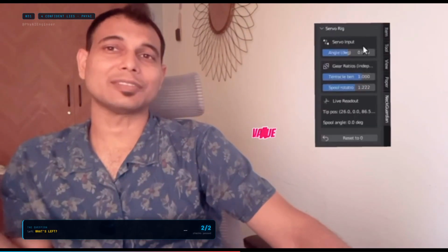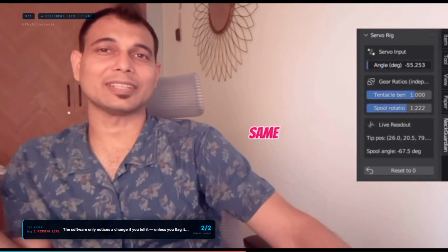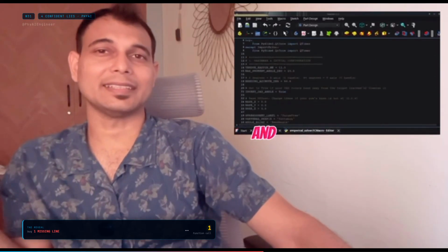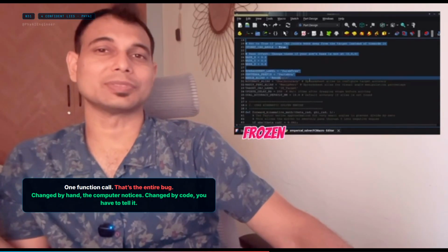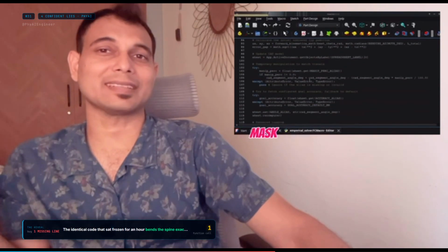Well, the software only notices the change if you tell it you changed something. Drag a value by hand in the interface, and it knows automatically. Change that exact same value in the script, which is exactly what a real servo command would do, and it stays silent unless you explicitly flag it as dirty yourself. One function call, that's the entire bug. With that one line, the identical code that sat frozen for an hour bends the spine exactly as much as the math says it should.